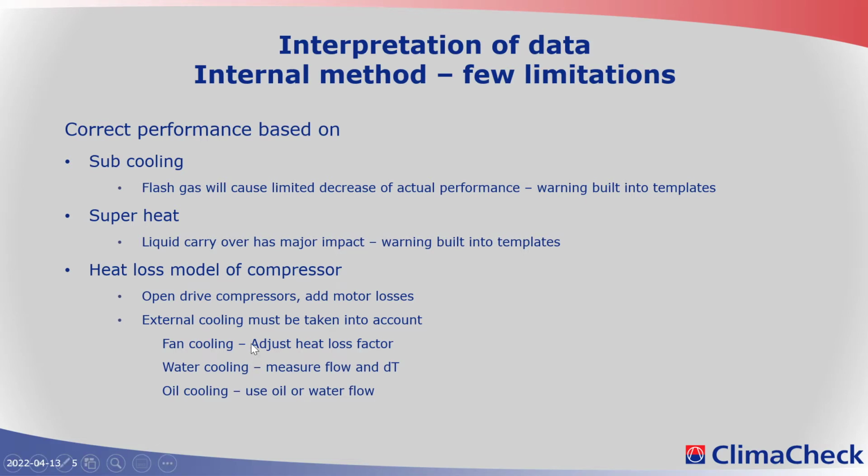Of course, check that your compressor seems to be running okay. A good compressor today is running around 70% peak isentropic efficiency. So you should be around there if it's full load, good conditions. For a low temp compressor, you might go down to below 0.6. So at very high pressure ratio, you lose isentropic efficiency. But make sure that you are in the right neighborhood.